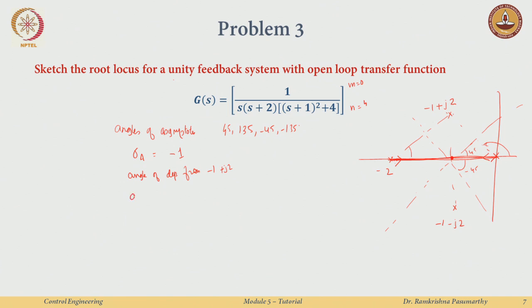So, that phi, the angle of departure, is just the negative, if all are poles, of 2 over minus 1 for the first guy, then you will have minus tan inverse 2 over 1, this guy is at 90 degrees, and then I add 180 degrees from the formula, and all this will just add up to minus 90. So, this guy will just vanish by itself, because you can also see the symmetry here. Okay. So, one thing I know is from here I am moving here, right.